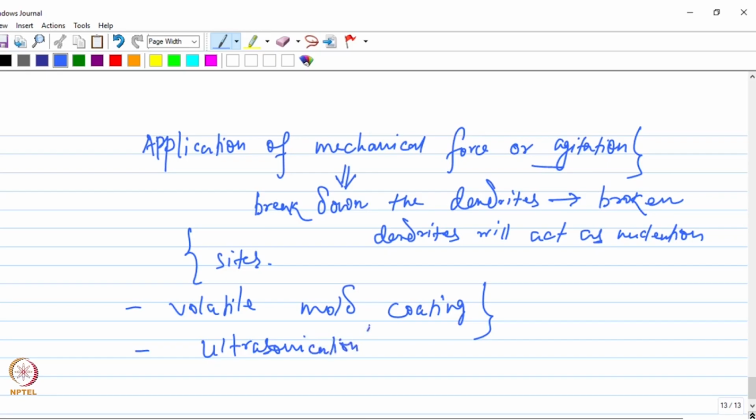In fact, this has become one of the popular techniques for grain refinement using the melting casting route. And it can also be done through a physical or mechanical stirrer. You physically stir the melt by using a mechanical stirrer. You immerse the stirrer and agitate it vigorously. That can also break down the dendrites, and a similar kind of stirring can also be generated by an electromagnetic stirrer.